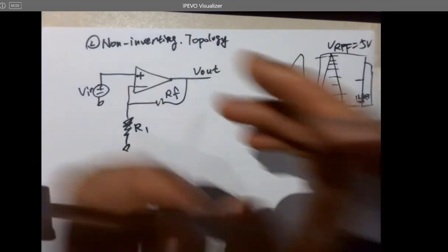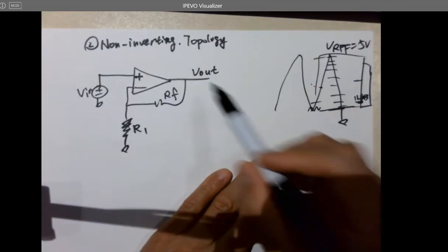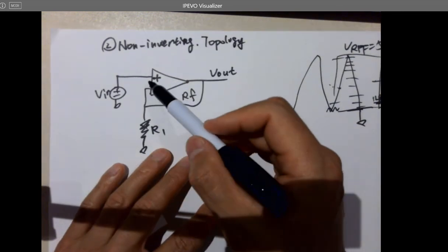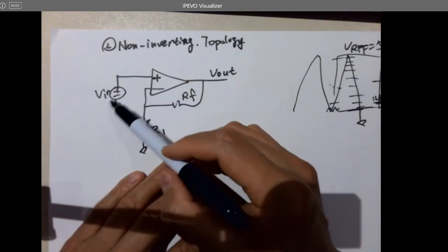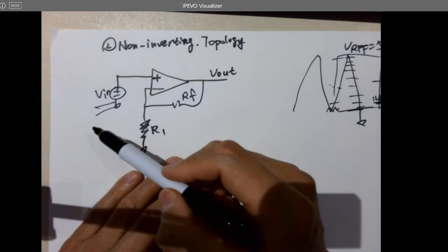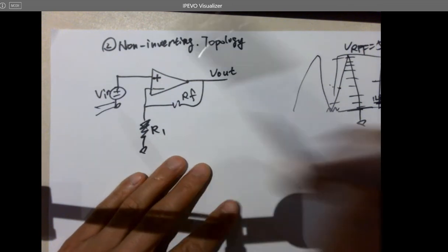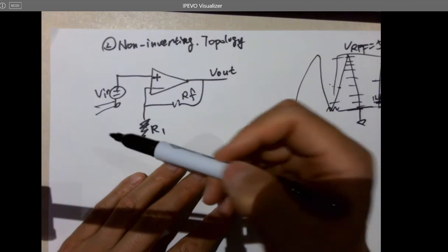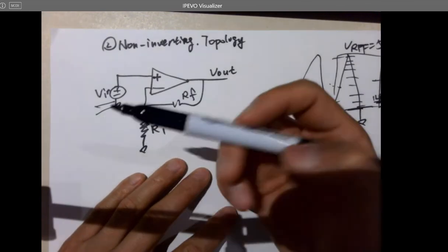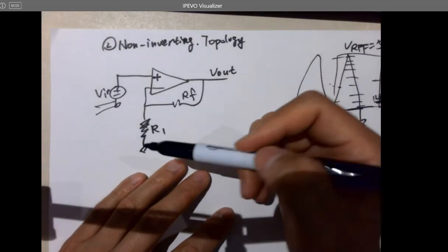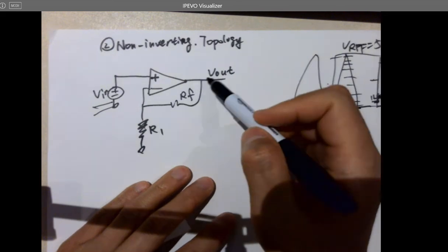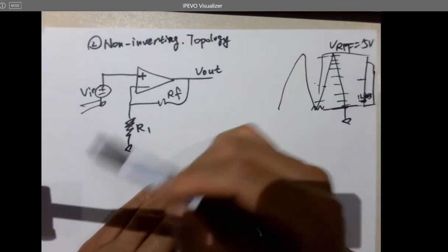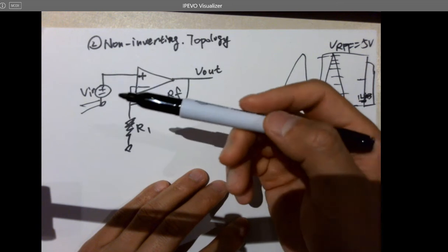But first, you need an ADC and amplifier. So the amplifier is usually put at the very front end, directly interfacing with the environmental parameters, which can be anything, like light intensity, temperature, humidity, acceleration, angle change. Any analog environmental signals can be converted into voltages. And sometimes you can have a current amplifier because some of the environmental signals are currents instead of voltages.